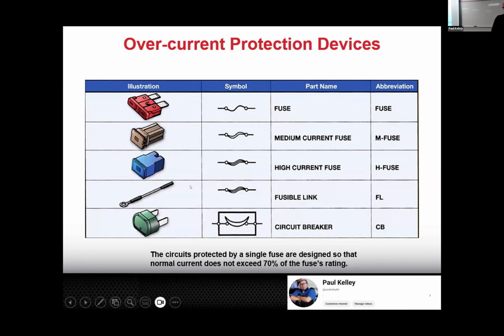But in fairness though, they're less and less common. They were pretty common on older cars, especially right there at the battery. It'd usually be if something's a major component, like they might have a fusible link for the alternator or something, because they didn't want to run big wires up through the fuse box. So I bet you will see them.